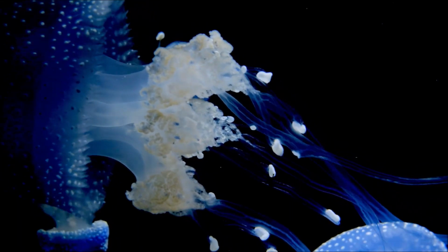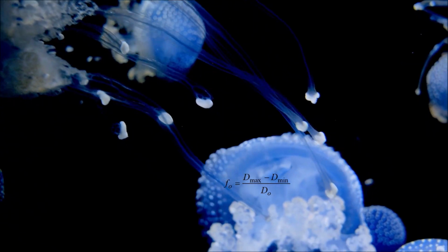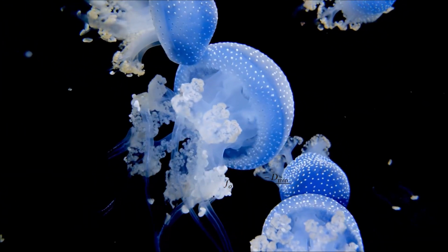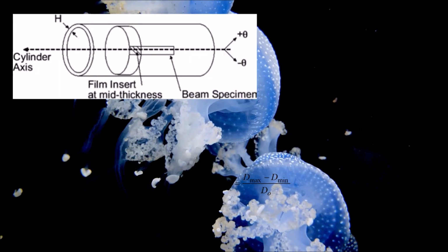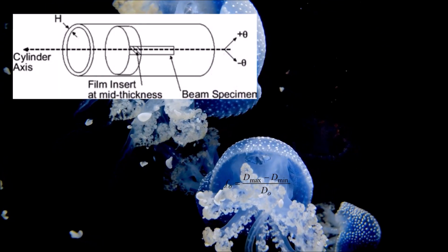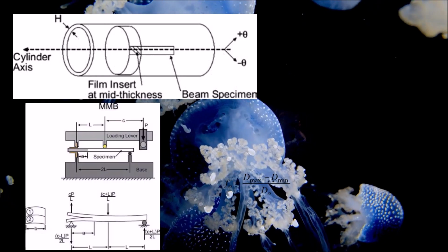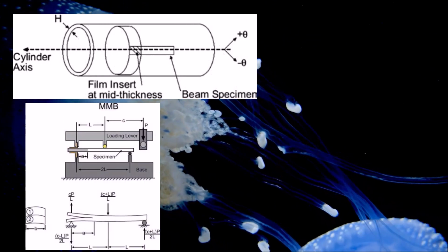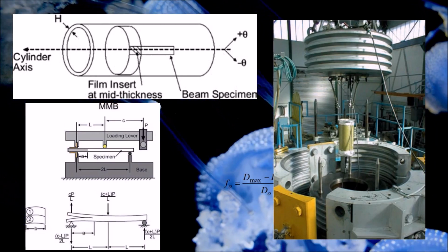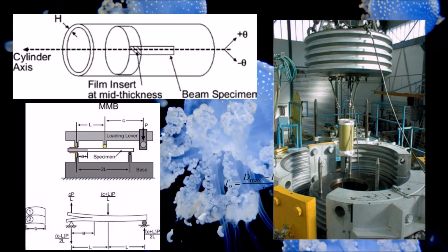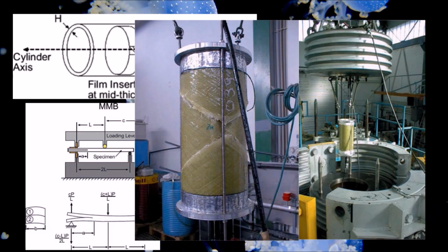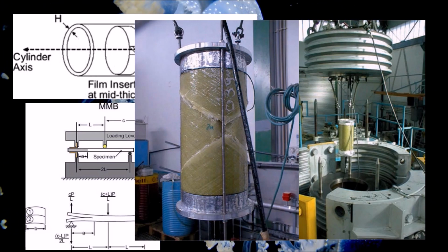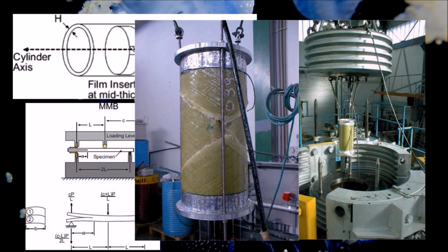A series of small cylinders were manufactured to investigate these effects. The cylinders were manufactured with artificially implanted film defects at different locations in the wall thickness to simulate delaminations. Delamination tests on extracted samples and implosion tests on cylinders were then performed. They reported that single delamination defects do not have much influence on the implosion pressure. However, multiple delaminations do have significant impact on the implosion pressure.